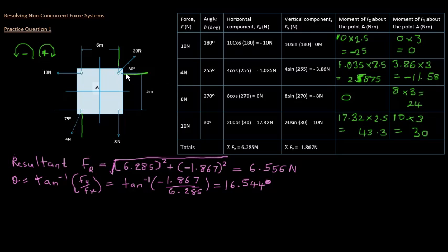And then you consider if you hold it here and you pull on this corner, it's going to spin that way, you can see. So now we've got all our moments, so this is going to be negative, because anti-clockwise. Now all we have to do is to add all these moments up together to get the sum. That's the total of the moment. On the calculator, it's going to be 3.2985 Newton meters. You can check that on the calculator.